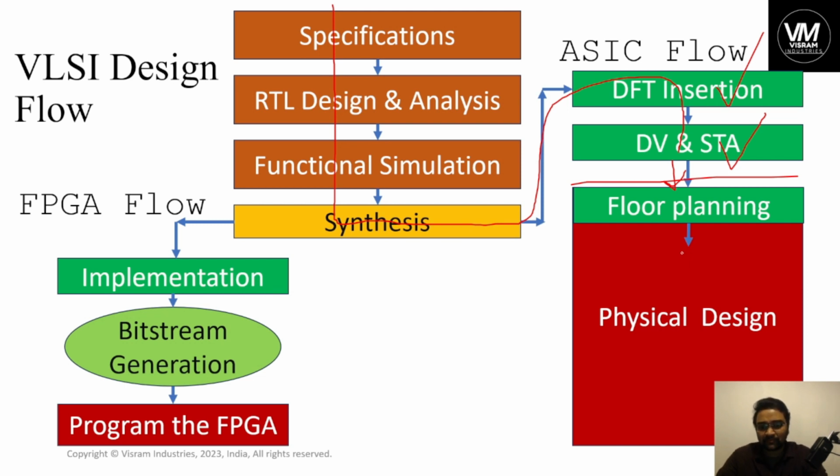Wherever you see some analogy here in this physical design, in the same way we will be setting aside, okay, ports should be on the external side, on the top, left or right in the block. So also you can see some memory blocks should be here, and clock cells can be sitting in the center of them. So it will be based on the specifications.